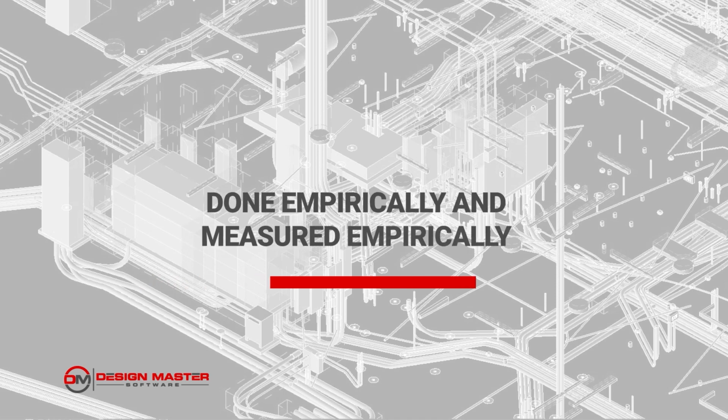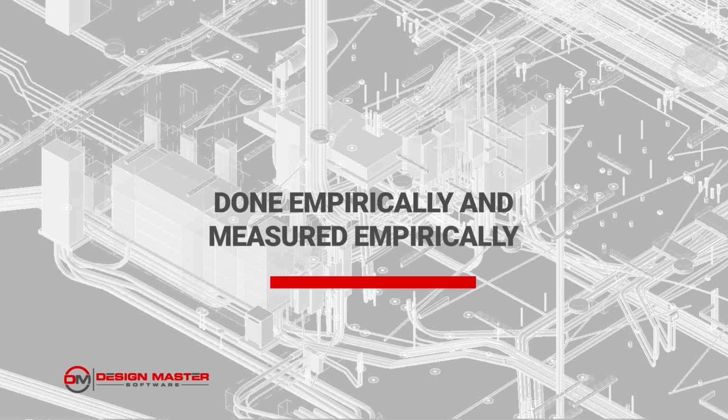So realize when you're using these calculations, it's not the precise calculations we have for a voltage drop or for a short circuit analysis. This was something that was measured empirically, and then curve fit. So just keep that in mind when you're using these calculations: in terms of the precision, don't get too caught up in having things correct to multiple significant digits, because the calculations and the formulas probably actually aren't that accurate. They can get us directionally in the right spot in terms of having safety, and it's important to run these calculations. Realize there's a wide margin of error on these calculations.